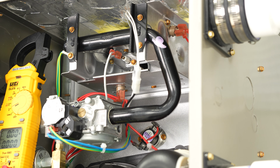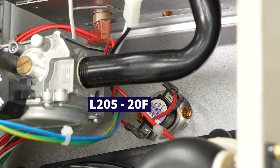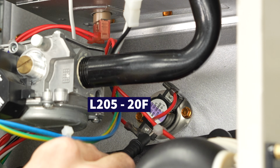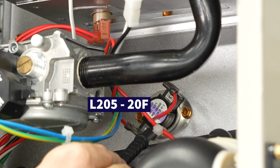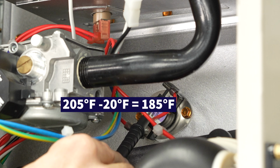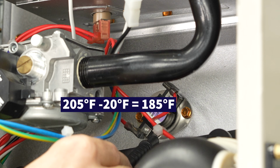But that one, once again, automatically resets, and the temperature measurements are on here, right here. So it says L205 minus 20 degrees, and so if it gets up past 205 degrees, it's going to open up, and it will close back down once it gets down to, say, 185, because you take 205 minus 20 and you're at 185 degrees, that's when it's going to close again.